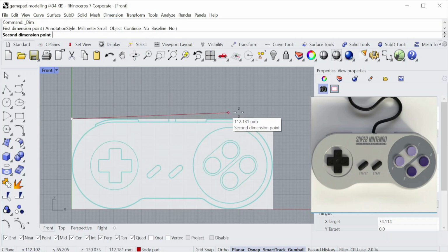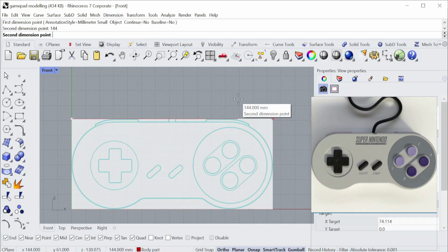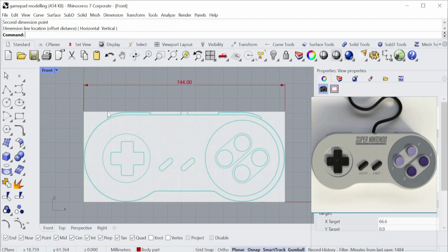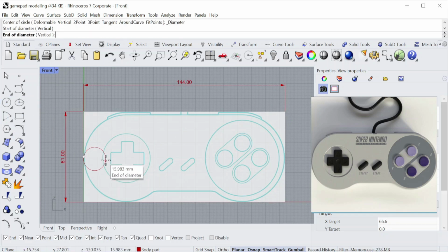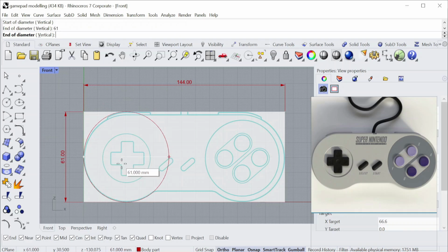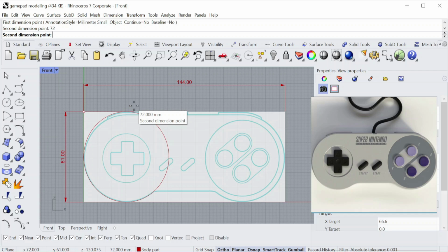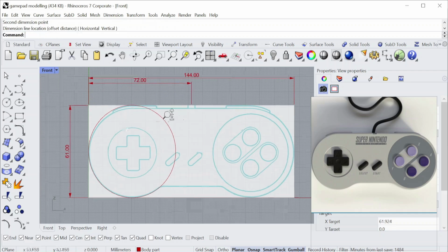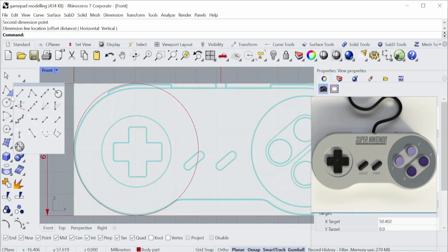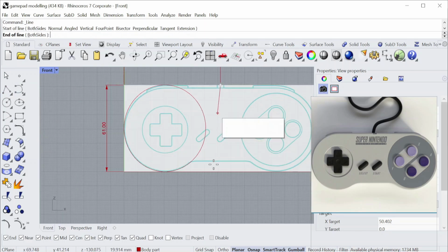If my drawings are not on the same plane, we can bring our drawings to the plane we want with the set XYZ's coordinates command. And if you notice in the video, I aligned all the drawings to the y-axis using this command. Then I used the arc blend command as a result of a small trim operation and completed the geometric shape analysis part by using the fillet command for the bottom of the model.